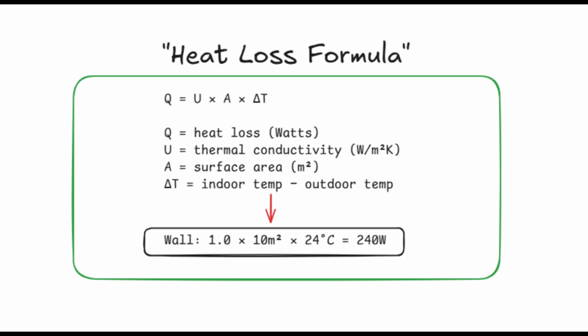First, surface areas. Every exterior wall separately, every window separately, the ceiling, the floor. Not just the total floor area of the house, every element that separates heated space from cold space. Get a tape measure or pull out your building plans.